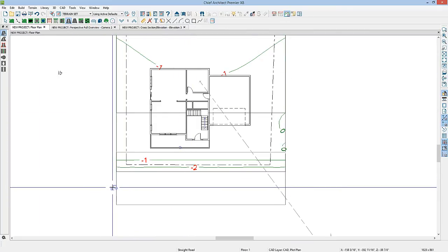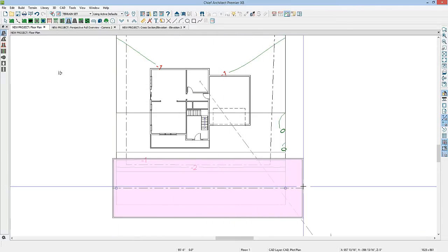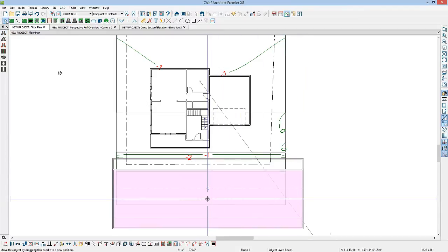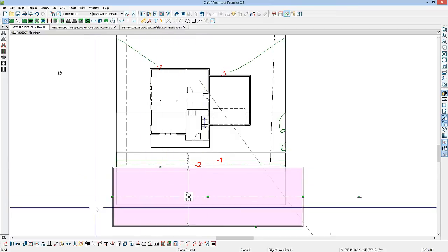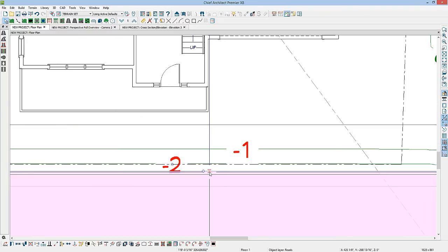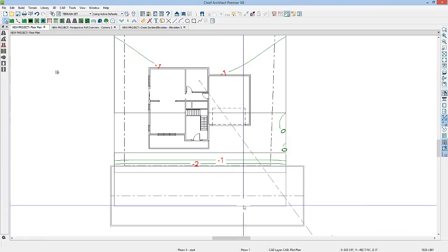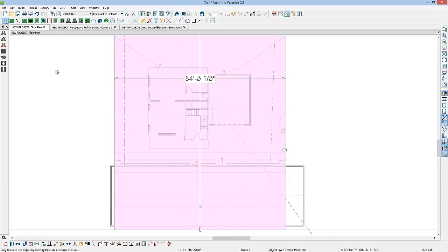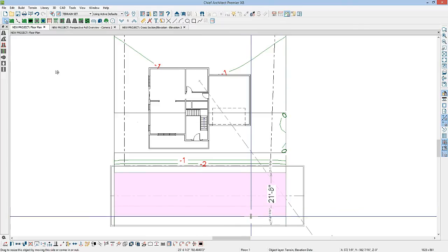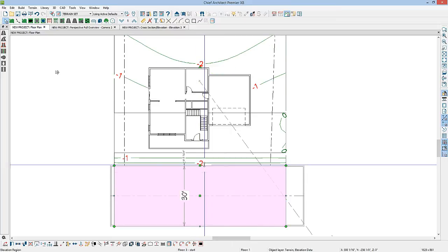I'm actually going to start this just outside of the terrain line and click and drag a road across the front of the terrain. And then I want to move this so that this roadway comes right to my property line. So here I want to use my point-to-point move tool. I'll zoom in a little bit, just click on the edge of the roadway and then click right on my property line. And then I want to make sure that the terrain edge goes all the way just past the roadway here. And then this negative 30-inch terrain region I'll use for the entire roadway. Take that right up to the property line as well.